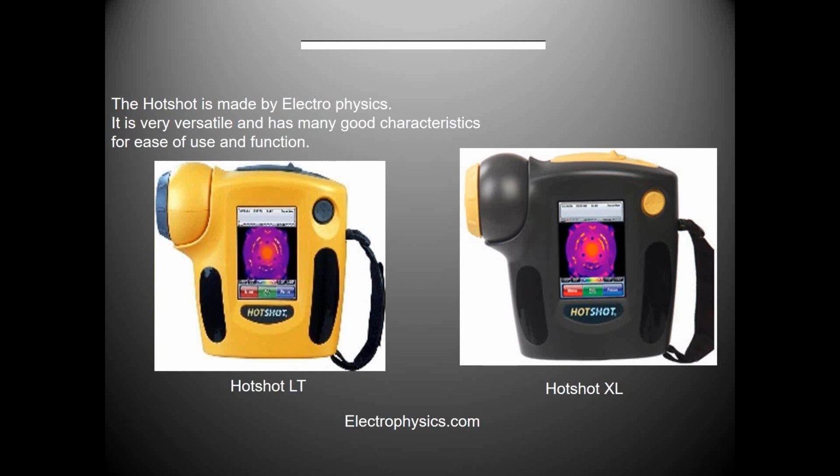I remember we used to do them once a year. Then we started doing them twice a year. Then we started doing mechanical inspections. Well, as you do these inspections, those all cost money the more times you bring the guy in. So now I wanted to put these tools in the hands of maintenance people so we can do thermographic inspections more often, sometimes monthly, sometimes weekly, and the tools are available now to do that.